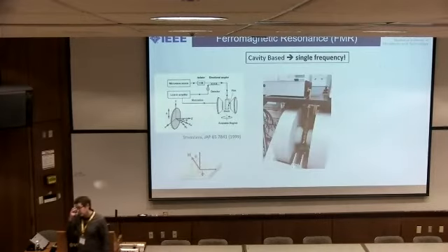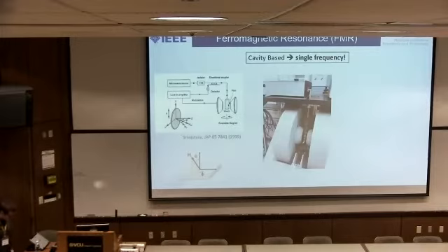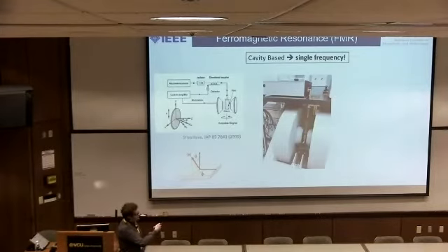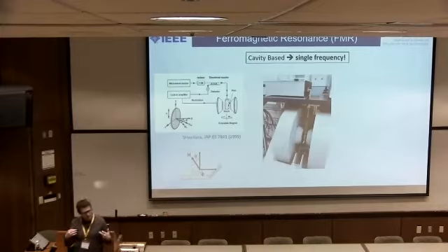Of course, we want to be able to measure that. So how do we do that? Well, originally it was done using cavity-based or waveguide-based ferromagnetic resonance techniques. This is an example, and it goes back to the 60s and 70s. This has been done for decades. It consists of basically a microwave source. It outputs some microwaves, 10 gigahertz, say, for example. And then they're directed down a waveguide. These are these copper or brass tube type waveguides. And they're designed to operate at a single frequency.